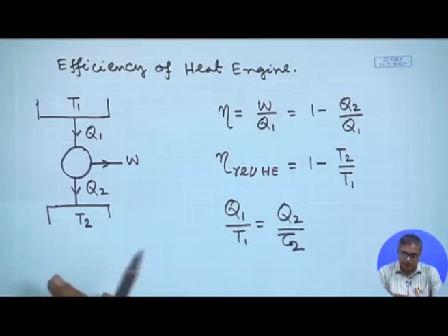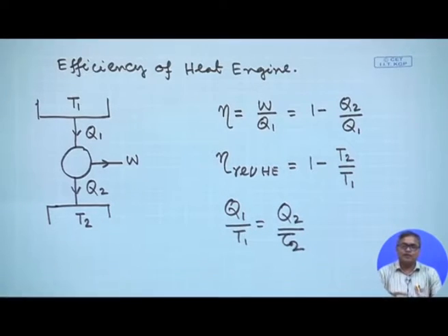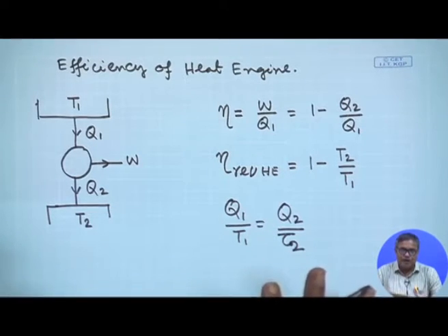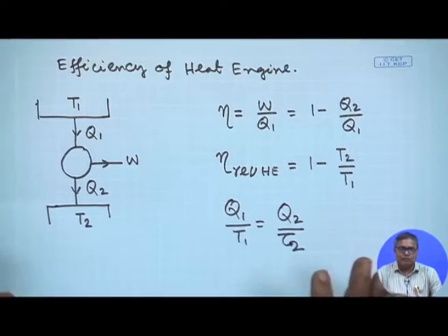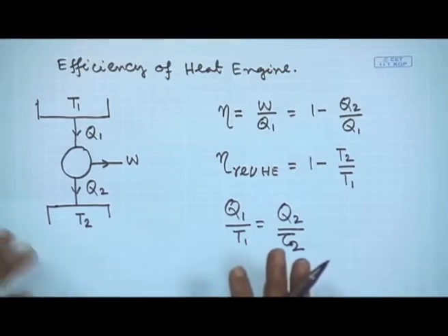So, when we were having the introductory lectures on waste heat recovery, I told that for waste heat recovery we have to look into two aspects. One is the quantity of waste heat we are getting, and another is the quality of waste heat we are getting. So, here we get a concept of quality of energy, which is also given by the second law: the quality of thermal energy is associated with the temperature from which the thermal energy is extracted.